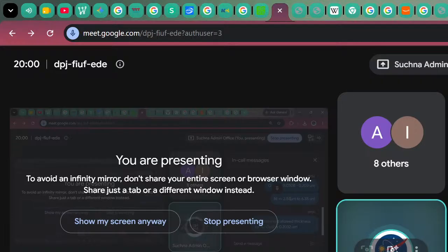Actually, I am telling you 7, which many people are using, but it is actually not allowed. It should be something like 4 to 6.35, but many people rounded it off and started using 7 micrometer. As days passed, this became a standard range. According to IPC 4552, it should be within 2.54 micrometer to 6.35 micrometer, but as time passed, people rounded 6.35 to 7 micrometer and started using it in some scenarios, and thus the standard range became 4 to 7 micrometer. It is no more 6.35. Some people are using 7 as well. So they chose a standard range of 4 to 7.